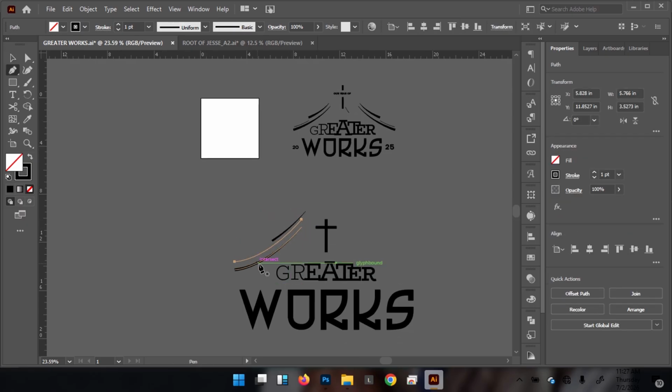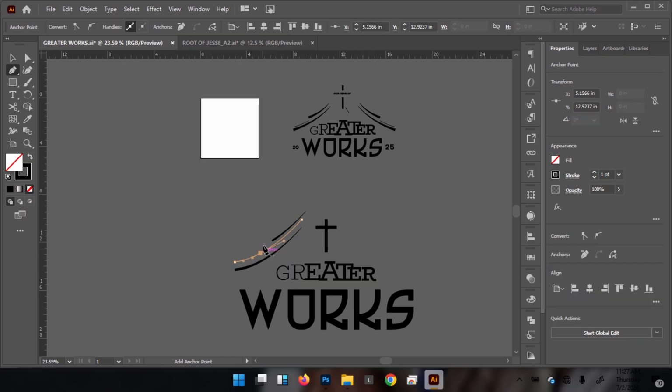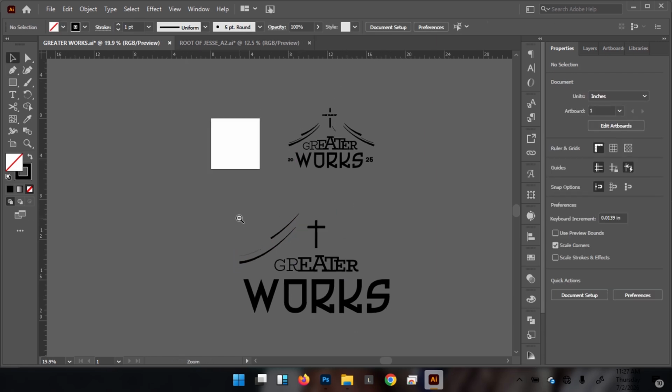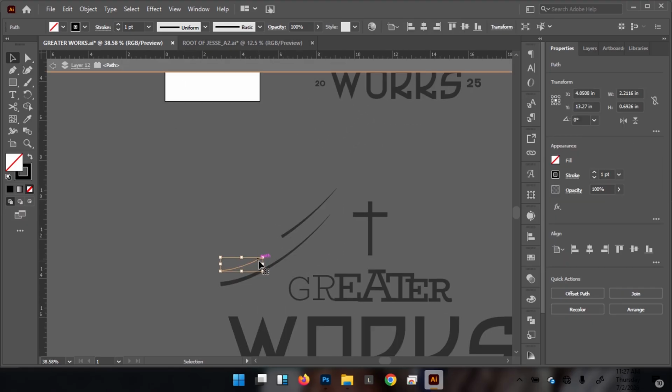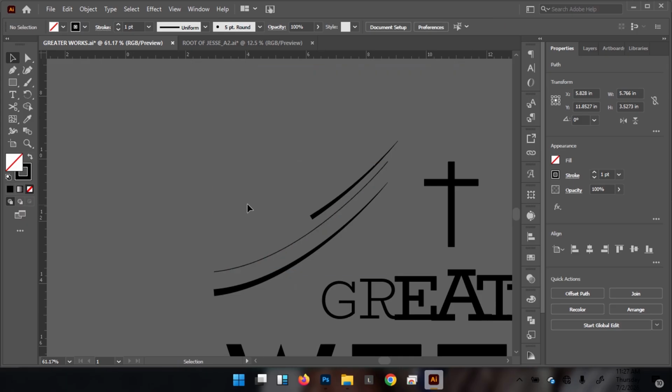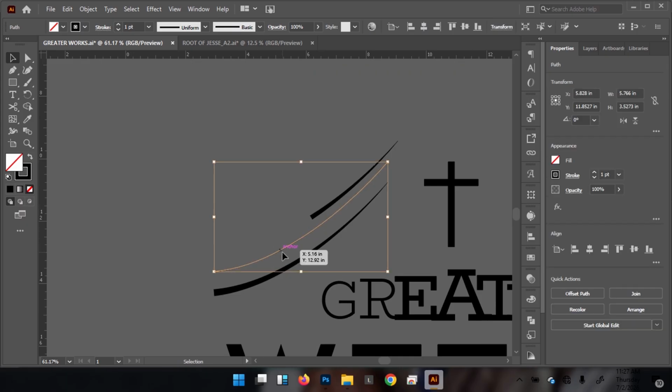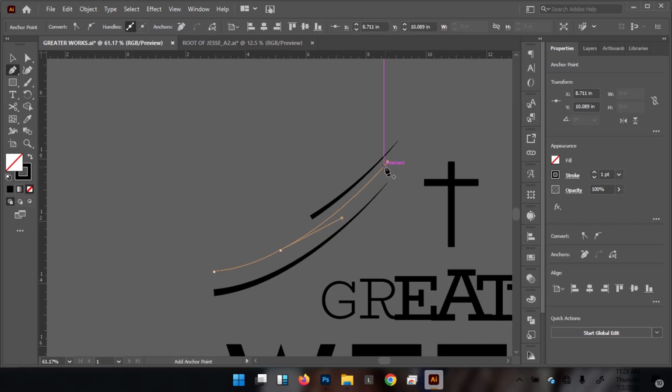Select this. P for the pen, click here. Click plus on the keyboard to add a point. And then minus, and then click on this point to subtract it. So just like that. Okay, you move it here. P for the pen, minus and subtract this.